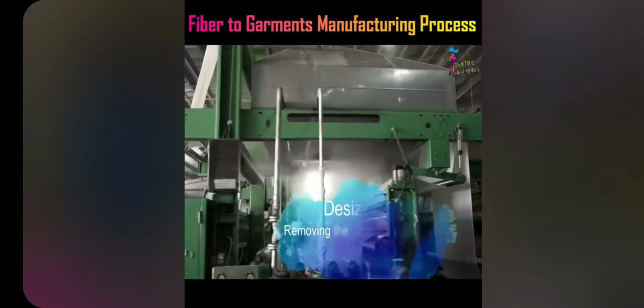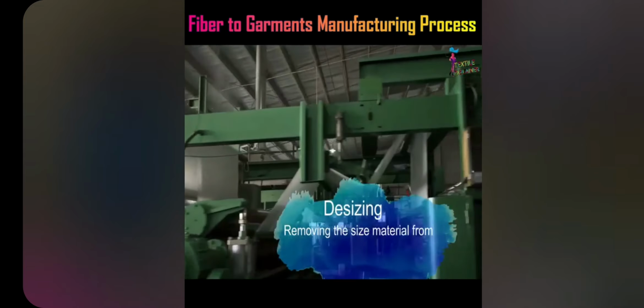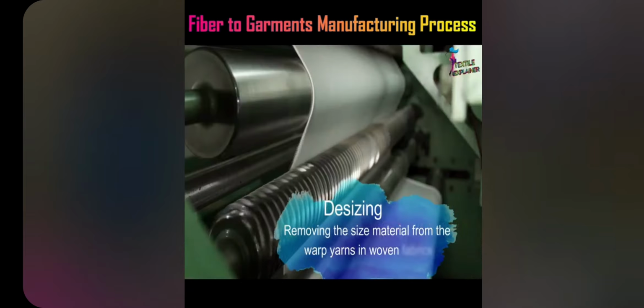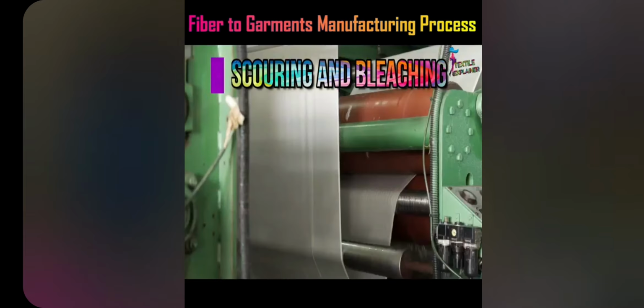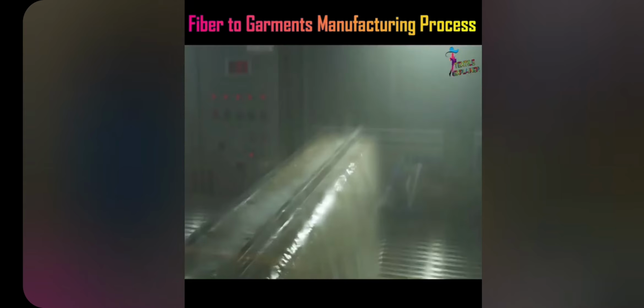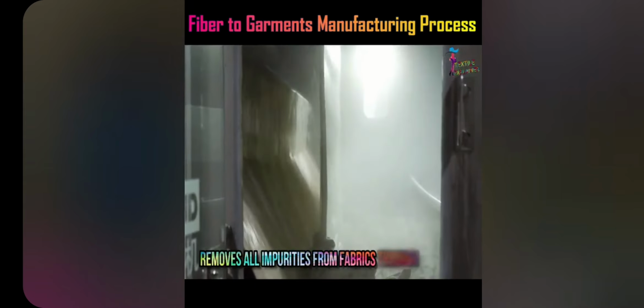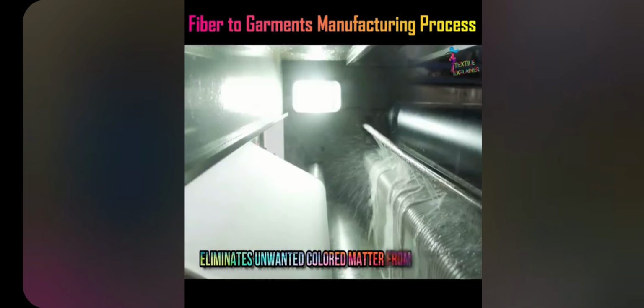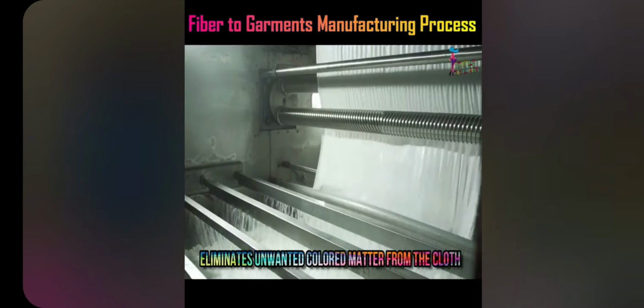Desizing. Desizing is the process of removing the size material from the warp yarns in woven fabrics. Then the fabrics go through the scouring and bleaching process, which removes all impurities from fabrics through washing and eliminates unwanted colored matter from the cloth.